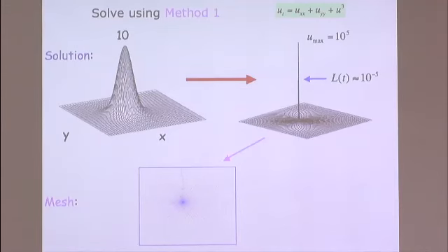These are the meshes that you generate. I don't know how well you can see it, it's a bit light. This is the mesh that's generated to get that singularity. And if you take that bit there and you expand it, it's beautifully regular. There's no skewness. It's as regular as you want, and that is a direct consequence of the regularity properties of the Monge-Ampère equation. This is what the solution looks like in the physical domain with this whacking great singularity.